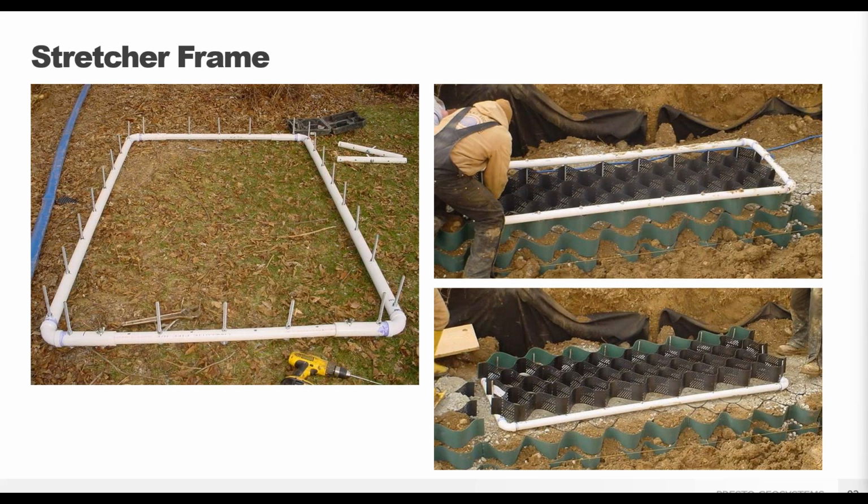Most of the examples will show wooden stretcher frames, but remember they can be made out of PVC or other materials and can even be adjustable, like this example. Use what works best for your site's needs. And again, if you're in doubt, contact our team, info@prestogeo.com, and see our case studies and resource guides at prestogeo.com.